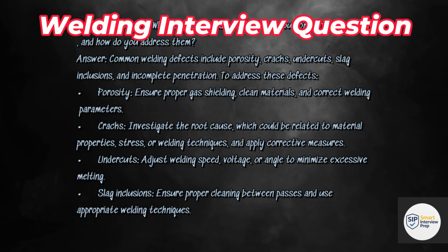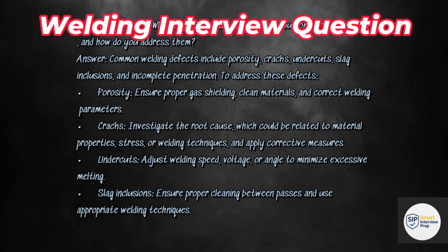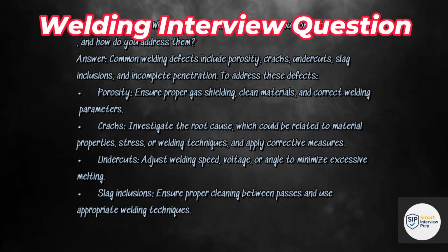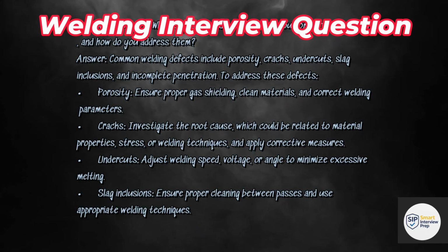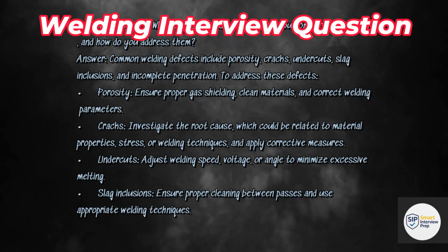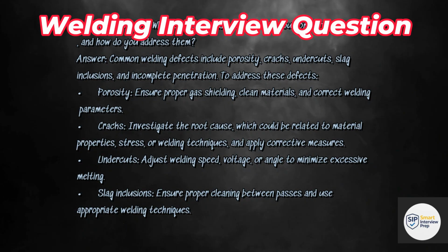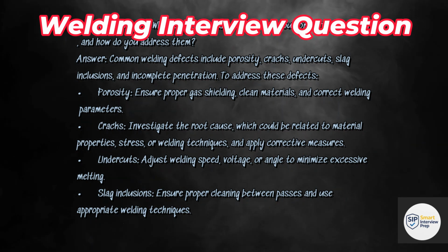Undercuts, adjust welding speed, voltage, or angle to minimize excessive melting. Slag inclusions, ensure proper cleaning between passes and use appropriate welding techniques. Incomplete penetration, adjust the welding technique or parameters to achieve full penetration.